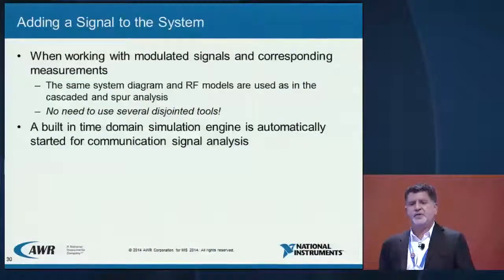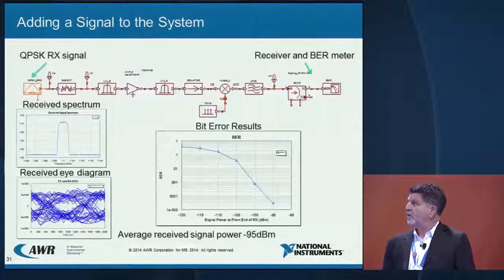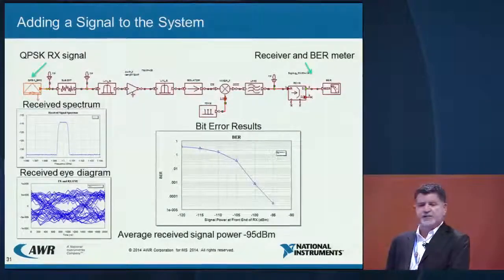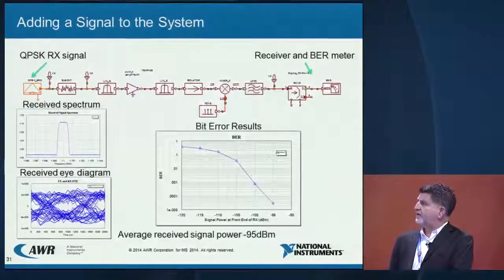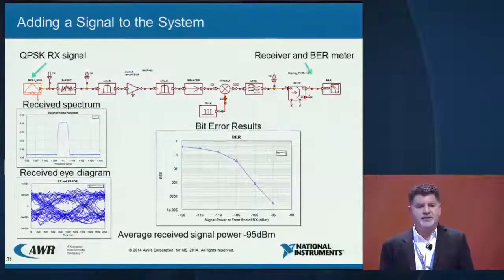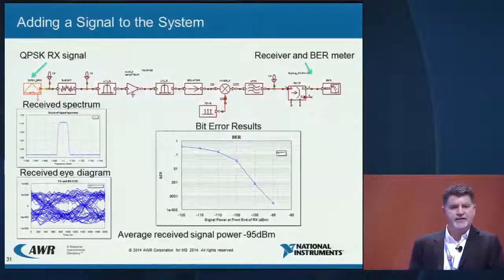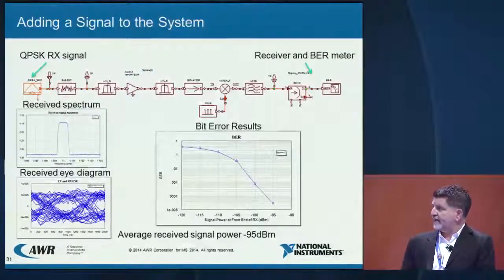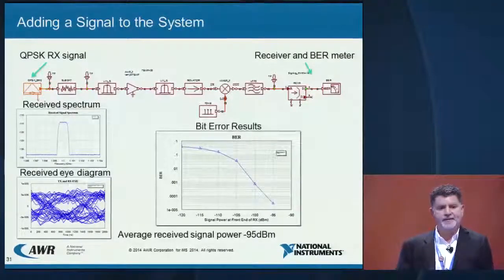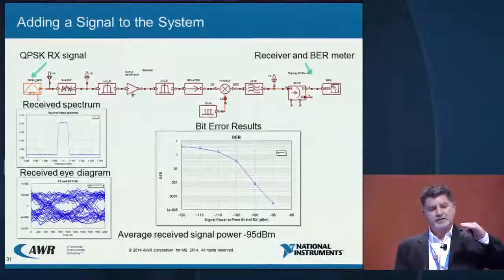So VSS supports many different measurements. It has two simulation engines in it. Once I switch to a communication standard, not only does the frequency domain analysis continue, but now we can look at time domain measurements, such as receiver sensitivity or bit error rate, and eye diagrams and spectrums. So from concept to a closer hardware implementation, all achieved in one tool.